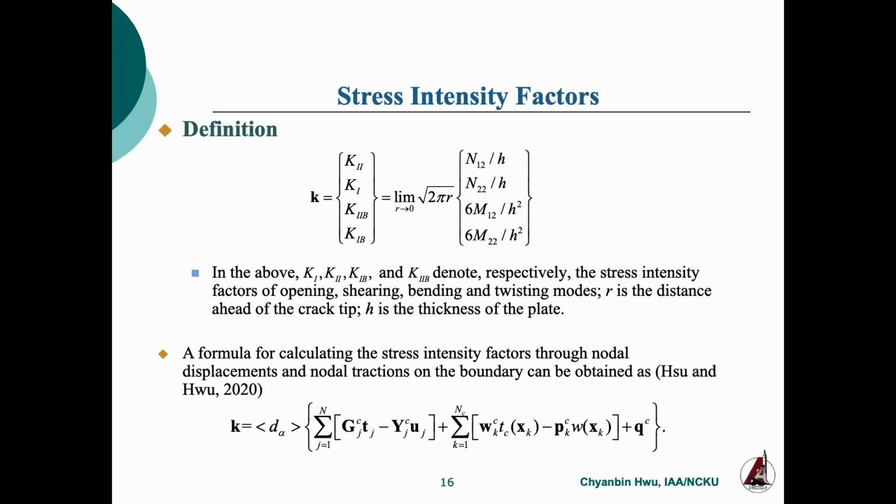So we need a formula to calculate the stress intensity factor through the nodal displacement and nodal traction on the boundary. This is quite important, because if you have the solution only on the boundary, and through this data you can calculate the stress intensity factor directly, then we don't need any mesh. This is the problem of the finite element. So we have this formula, and we derived this formula 4 years ago. And now it's very useful for us to do this work.